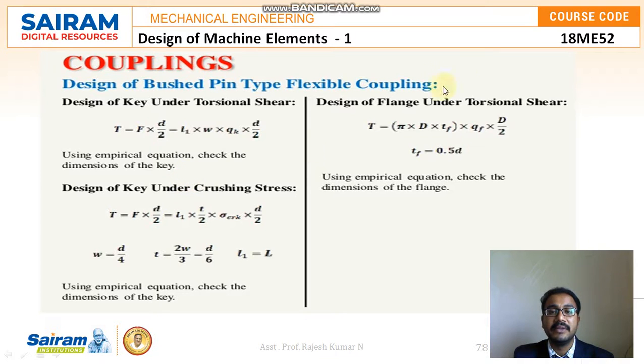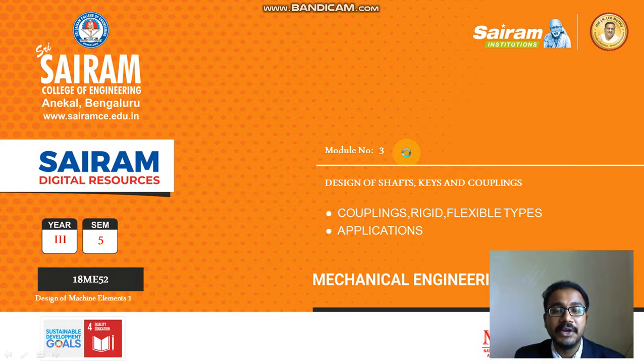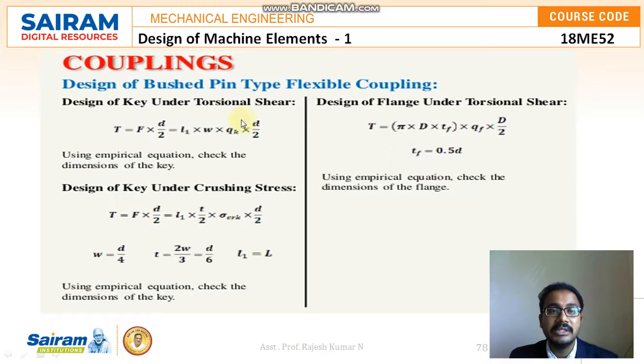And finally, the design of the flange, that is the thickness of the flange, we will find out by the relation 0.5D. So with this, I'll be winding up this video, and the numericals of these couplings we will be discussing in the upcoming video.